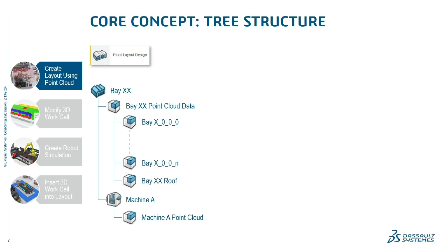It just makes it easier to get into it, because otherwise it's a cloud of points and you have to navigate around that. And then you have a DELMIA resource. In this case, we're showing a machine. It could be racking, storage. You could use robots, but typically you want those to be more dynamic. And under that, you would create your extractions to put your point clouds into. So keep your main area for the outline of your building, and anything you want to convert into resources, your machines, your shelving, create your resource, and then put a product node under that resource.